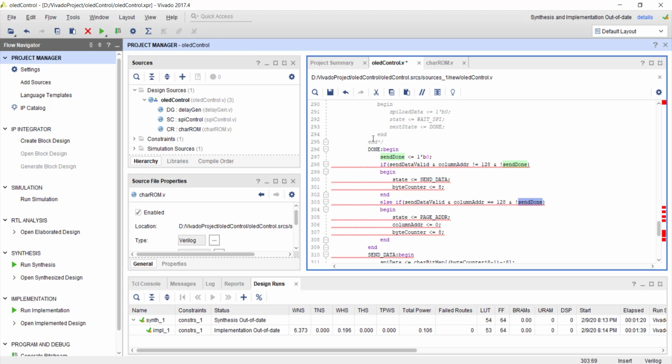Okay, so always keep this in mind, the handshaking signal. When two modules are doing handshaking, even if you make a signal high, the other module will see it only in the next clock. So only in the next clock he will deassert his valid signal. So you have to wait 1 more clock before checking that valid signal. Otherwise you will see the same valid signal twice and you will be sending the same data twice, which is problematic, actually always.